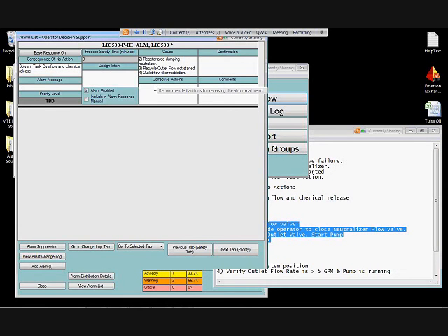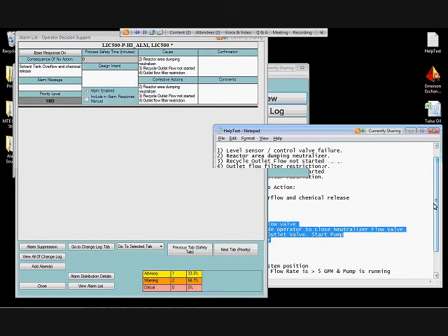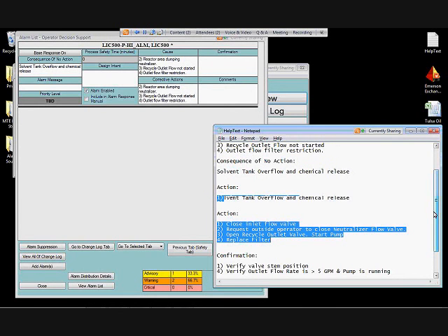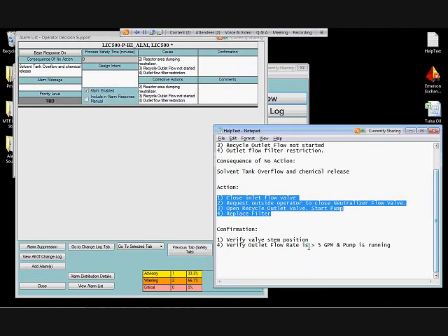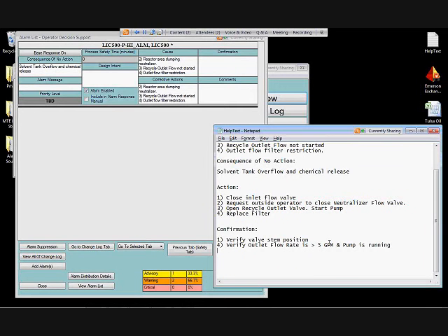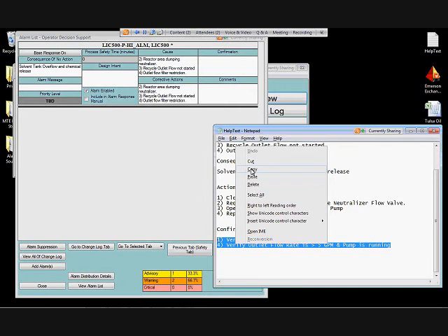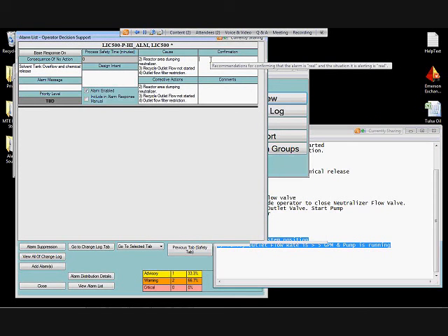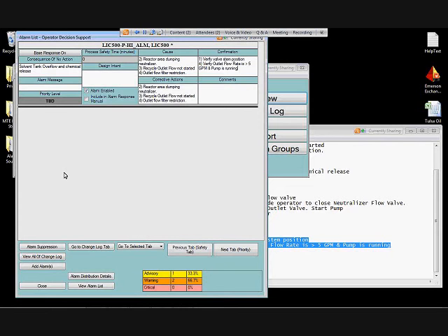And you can see this is kind of a knowledge capture process, documenting what your best operator would do in response to an alarm. So in addition to accomplishing rationalization, we're also doing knowledge capture. And then he's also told us how he would confirm that the alarm is legitimate and troubleshoot and determine what the actual situation is. So we'll record that information. So now we've got everything, and based on what we see, it's got significant consequences. We've defined what the operator's supposed to do. So yes, this is a legitimate alarm, so it's supposed to be there.